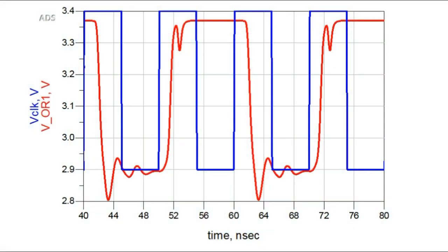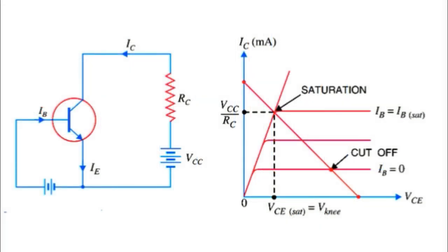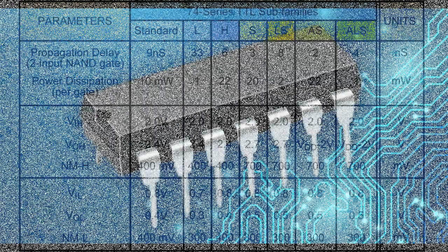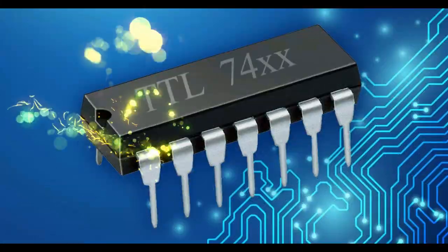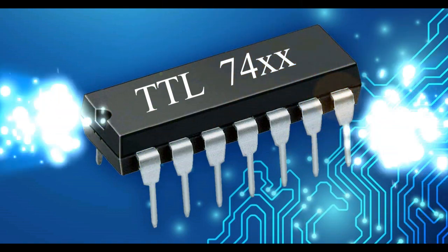But noise has a greater effect in ECL logic, because the unsaturated transistors operate within their active region and amplify as well as switch signals. With improvements in the circuit design to take account of propagation delays, current consumption, fan-in and fan-out requirements, etc., this type of TTL bipolar transistor technology forms the basis of the prefixed 74 family of digital logic ICs.